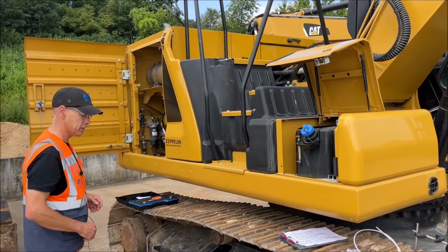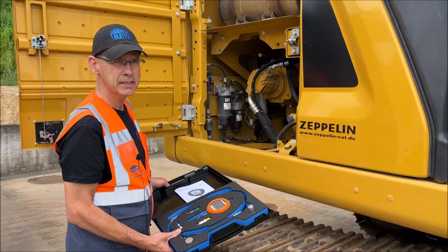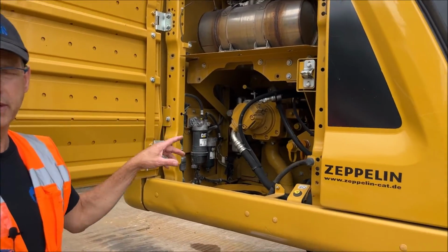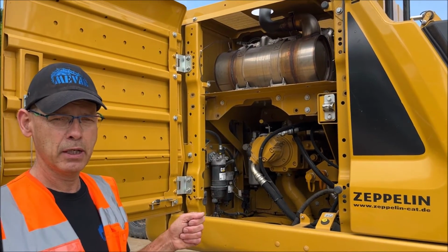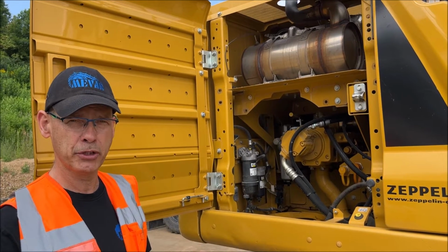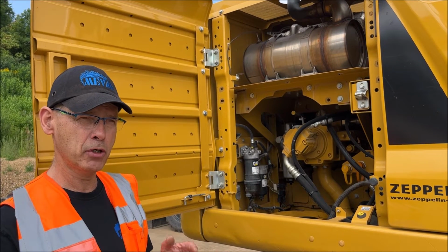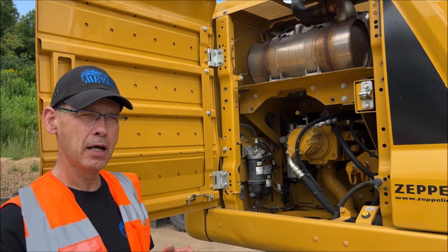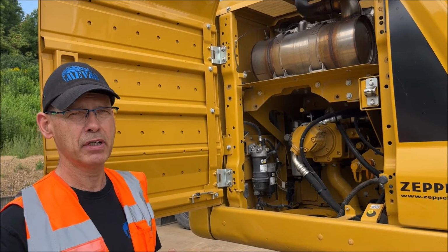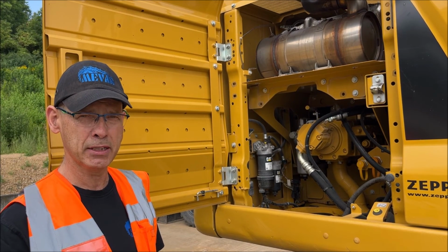Last but not least, we have the tools for pressure testing. Most machines have sockets available where you can plug in the gauge and take the main pump pressure and the pilot pressures, or any other pressure that the customer requires. Those pressures can be compared with the factory specs, and someone who understands machines can estimate if the pump and the hydraulic system is in good working order, or if there is an adjustment required.